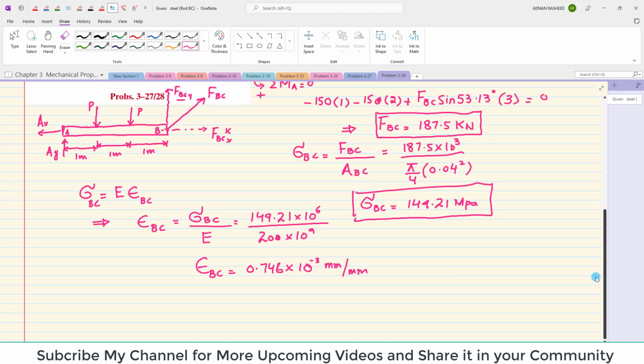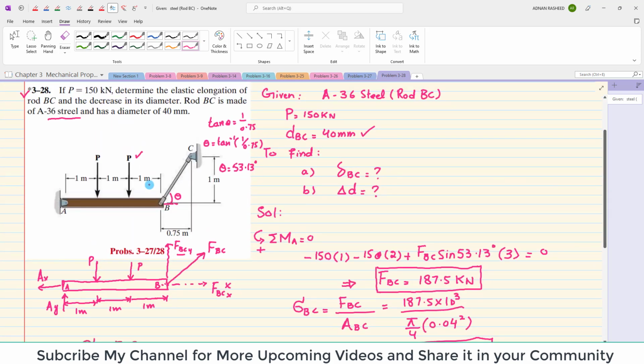Now you have this strain. From this strain we know that strain BC is equal to change in length of BC divided by original length of BC. Now original length of BC can be found out by taking the Pythagoras theorem. So length will be equal to square root of 1 square plus 0.75 square, and when you calculate it, this length will be equal to 1.25 meter, or 1250 millimeter. So this is the length of this rod BC.